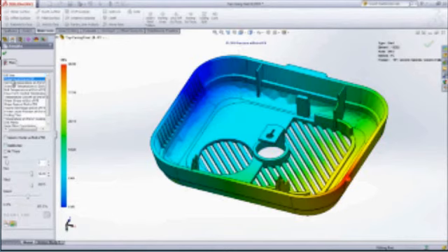However, you can see that with 47 MPa, our pressure to fill is still somehow high. We still need to get this lower, considering that we are looking at a single part cavity, and the injection pressure requirements will increase when we move to a multi-cavity mold configuration with sprues and a runner system.